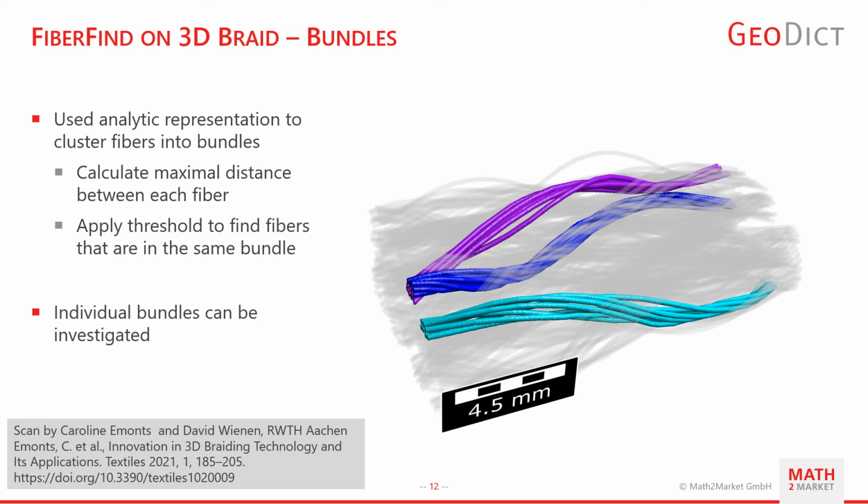So now you can not only get insights about your fibers, but you can also better understand how your braiding process creates these bundles and what the properties of your bundle are. So for example, analyze what is the minimum and the maximum diameter of my bundles, what is the porosity inside of a bundle, and stuff like this. So basically anything you can come up with.